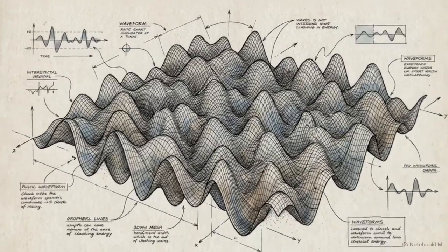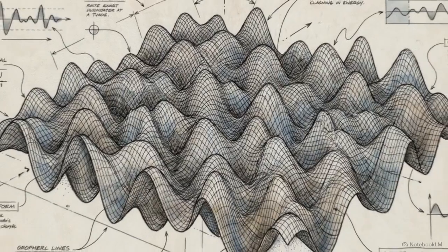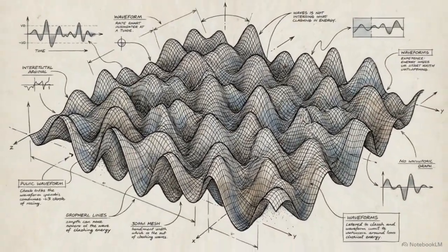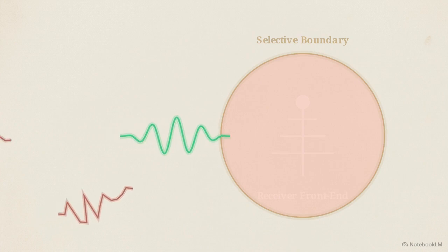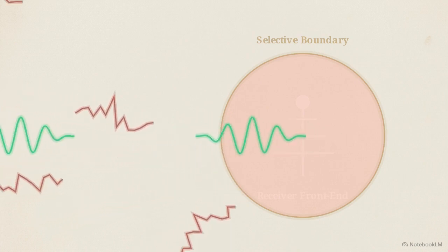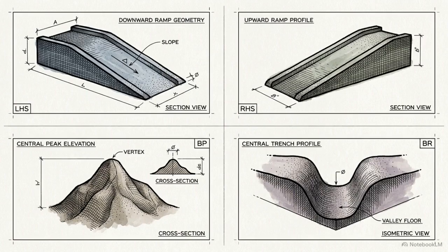The modern wireless spectrum is a densely packed environment. Thousands of invisible data signals overlap in the space around us constantly, creating a high-density sea of electromagnetic energy. A primary requirement for any wireless receiver is the ability to distinguish its intended signal from the interference generated by neighboring bands. To achieve this isolation, engineers rely on four foundational filter architectures: low-pass, high-pass, bandpass, and band reject.